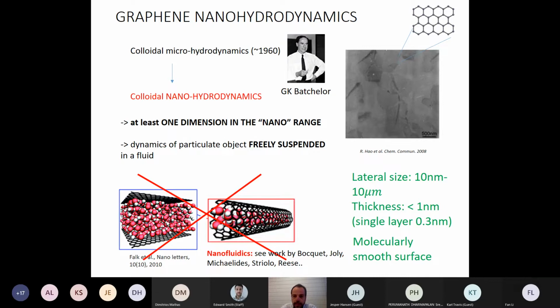And it's a very sophisticated field in which theoretical and numerical solutions for the stresses around a single particle are used to extract properties for an entire suspension via averaging methods.